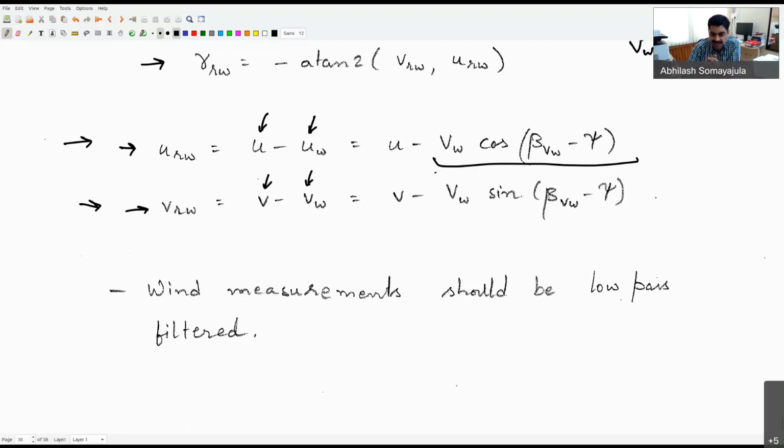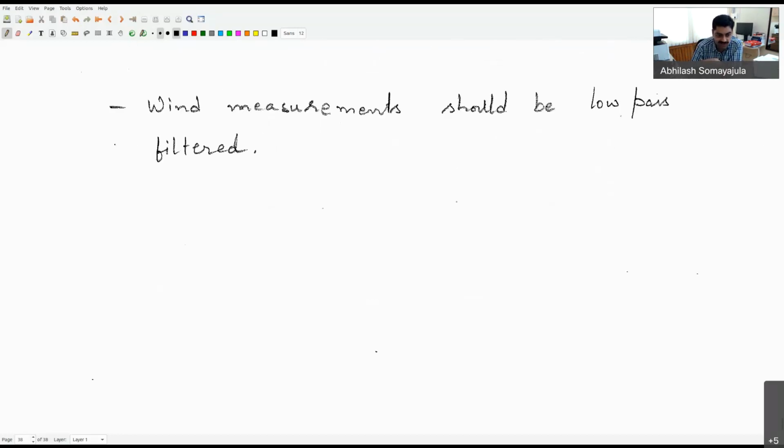Now, there are times when you want to move away from the PID system and look at different controllers like the nonlinear controllers. Some of the typically popular nonlinear controllers would be LQR, which is the linear quadratic regulator, or a backstepping controller, which is basically trying to find a control law using the Lyapunov theory such that the controller is going to be stable enough.